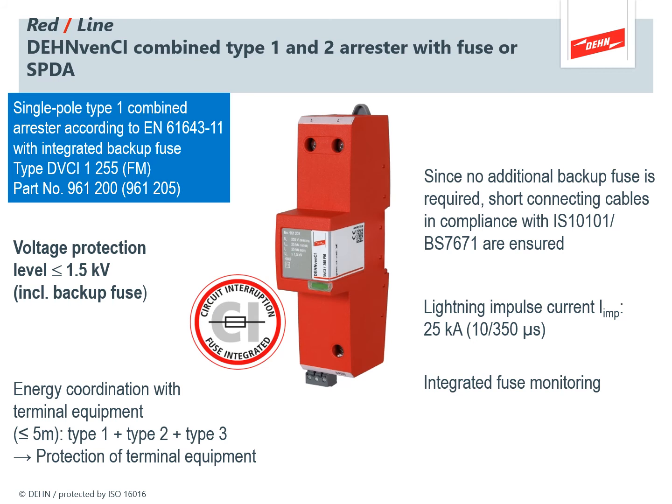So it's a very good product if you're looking to integrate the fuse in and have all the problems associated with dimensioning of the overcurrent protection device. They simply all disappear now. You probably still want to fit an isolator in there so you can at least disconnect them for testing or maintenance or anything like that.